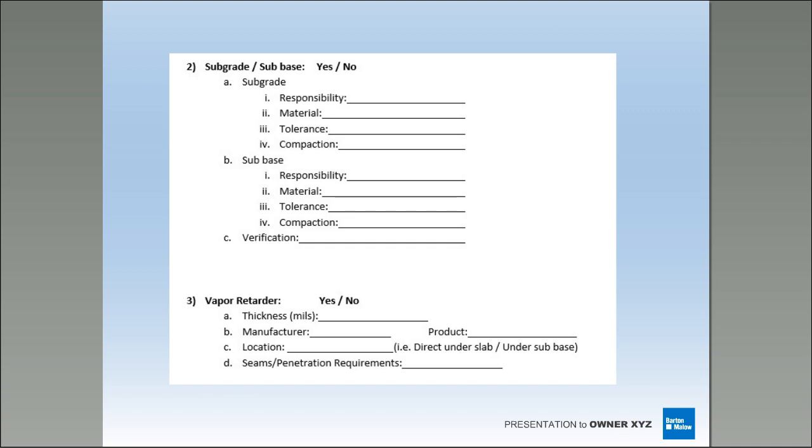So you want to know, does it have a vapor barrier or not? If it doesn't have a vapor barrier, what are my soil borings? Where's my moisture content in that soil? How much is it retaining? Because that's going to affect your curl too. I know it's a lot of information, but these are just some things to be aware of as you're going through a pre-pour.